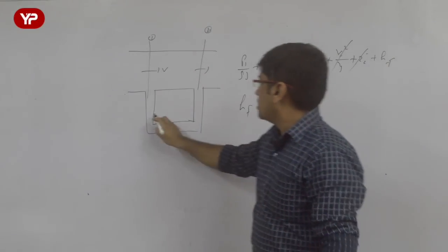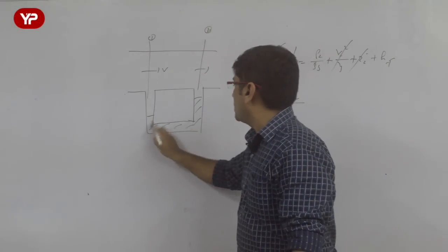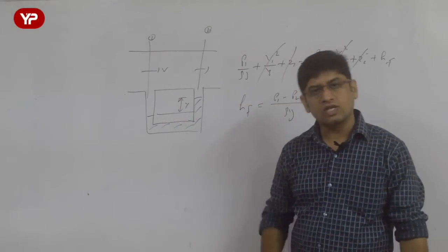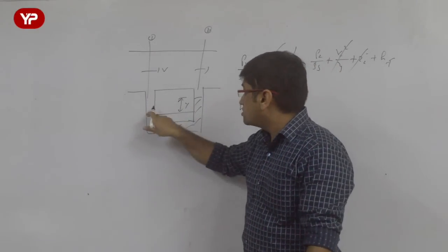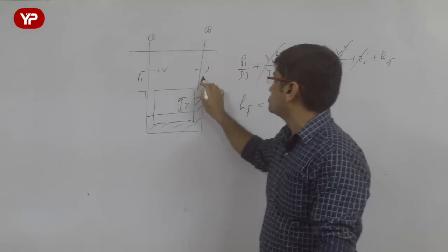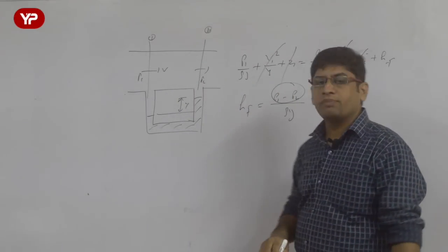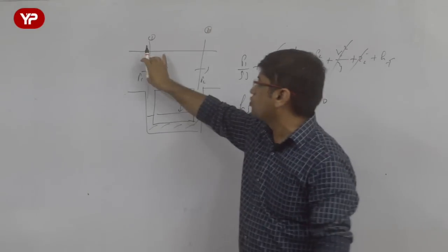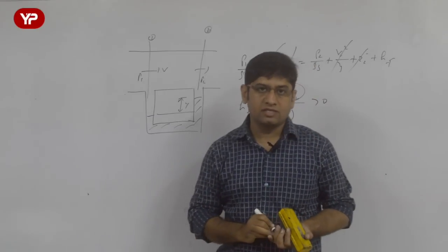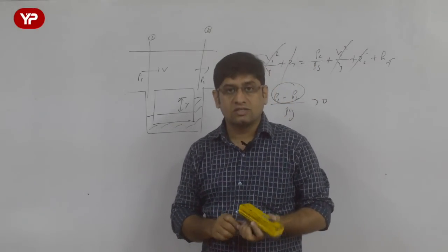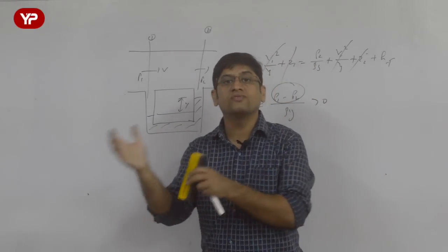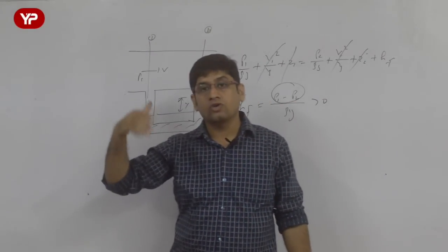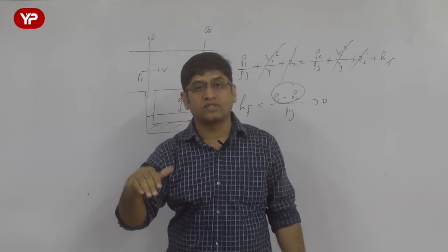Let us say through a manometer I came to know that the limb difference of mercury is like this. Study the manometer properly. This limb difference is telling you that P1 is more than P2. And if P1 is more than P2, HF is positive. And if HF is positive, the fluid flow direction is this. That simply means this pressure loss is the actual pressure loss because of friction. So this difference of pressure head is the loss of pressure head because of friction and viscosity.